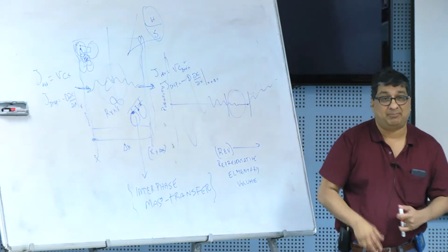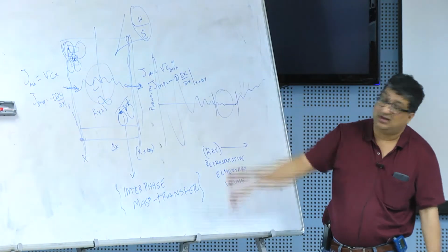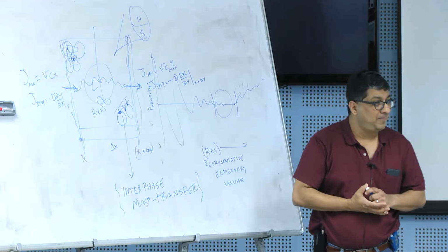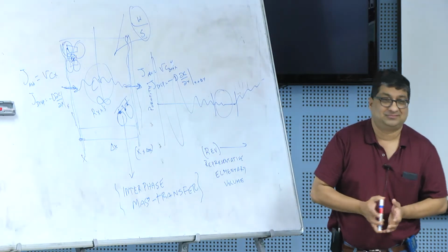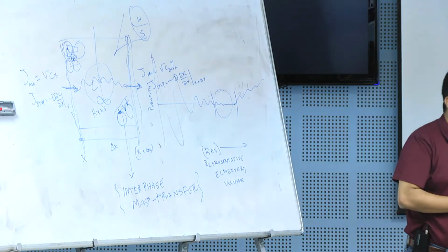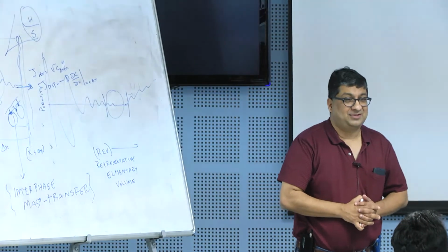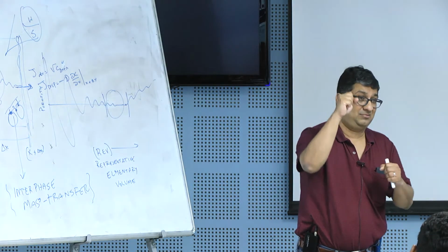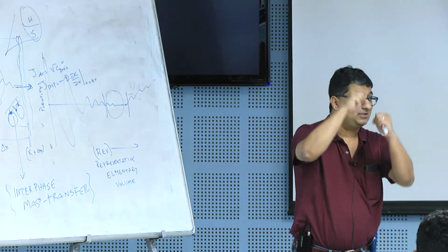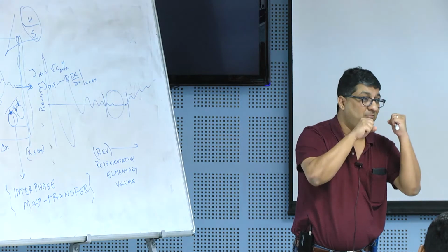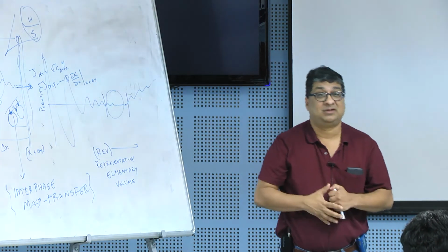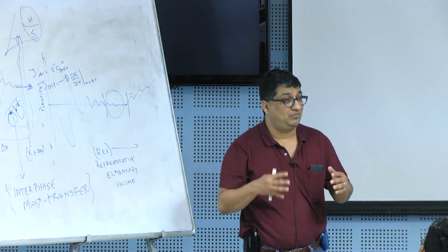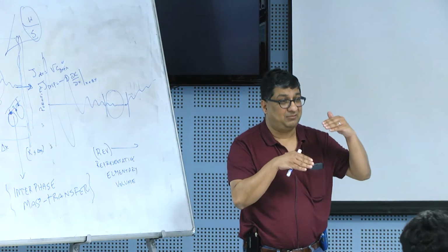What other processes can happen? Now, what other types of reactions can happen in your aquifer? The solution, that is a liquid-liquid mass transfer. Okay. So, yeah, you could have two fluids in your system that are immiscible, and things can actually move from one liquid phase to another liquid phase. So, that is possible. So, we can certainly have some in the vadose zone. We have air, so there could be volatilization or mass transfer between the vapor phase and the liquid phase.